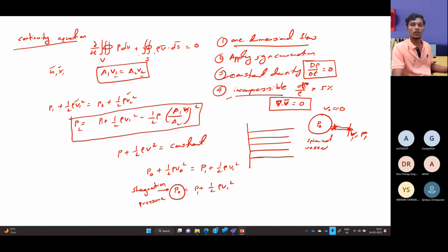but there is a significant velocity at the exit of the throttle or the exit of the opening. There we have the pressure P1, a different static pressure, and a different kinetic energy. This total pressure, or the stagnation pressure, is converting into static pressure and kinetic energy. This relation is only valid for the conditions of the Bernoulli equation, only for those conditions it is valid.